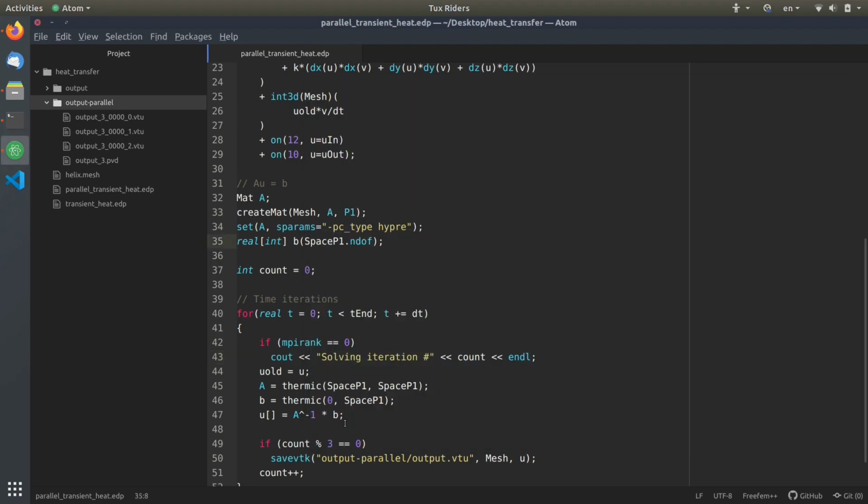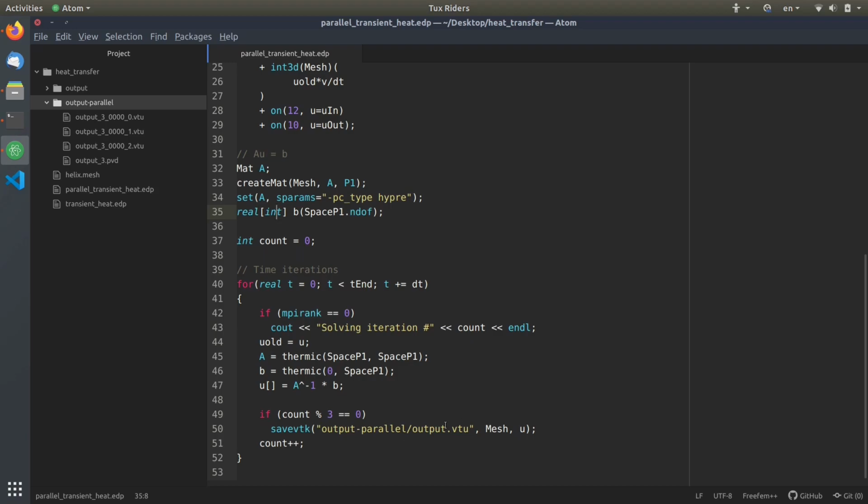And the reason is that I'm saving on the same file, so indexing is not a problem. But savevtk has an argument that says whether I should append to the previous results or overwrite them. So this is something very handy. We can use a ternary operator here, for if-else.